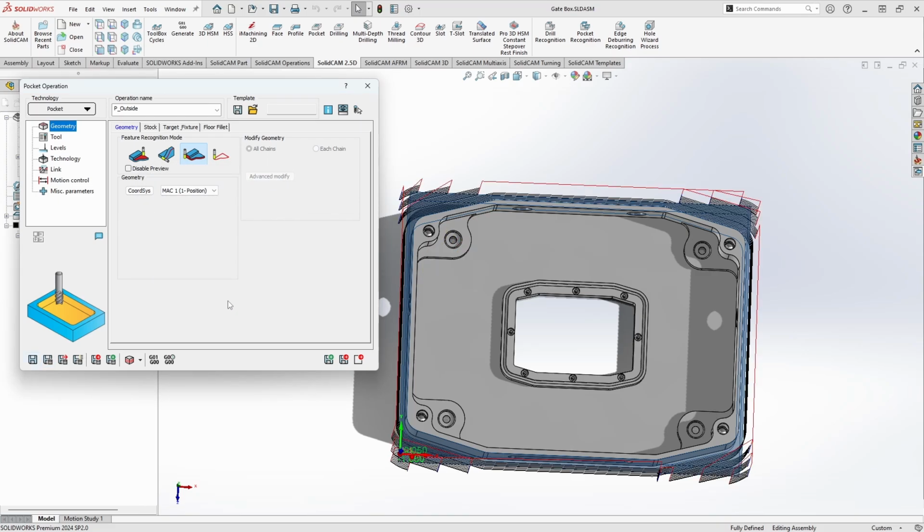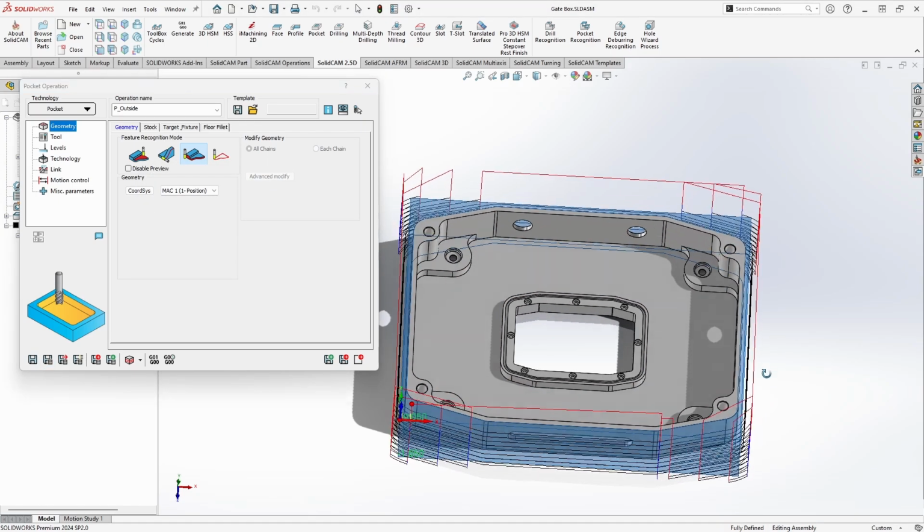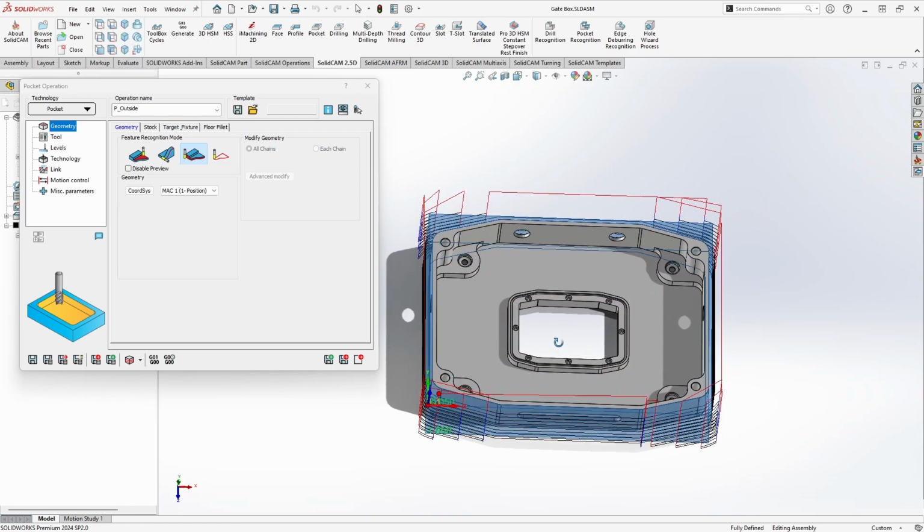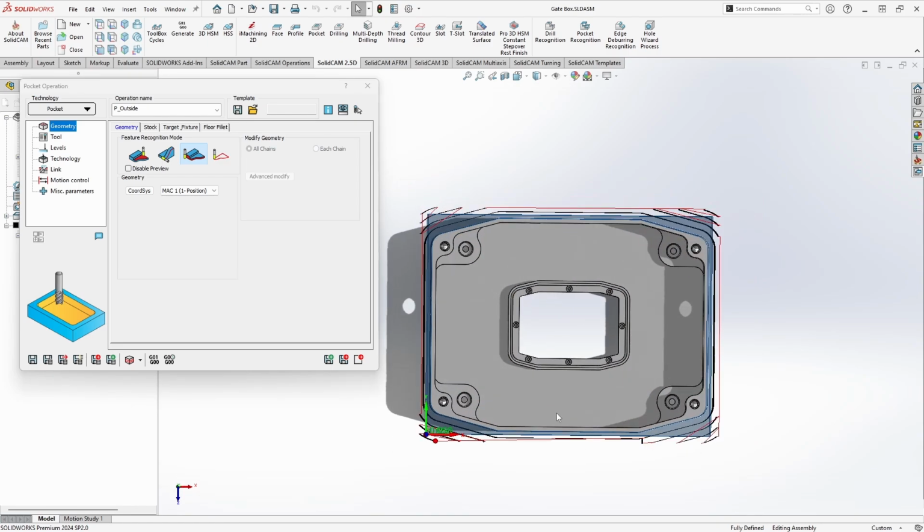you can see that we've generated toolpath only on the external sides of the part to remove all of the stock material that was present when we initially set up this CAM part. This is a super simplified one-click way of removing basically all of the external perimeter of a part without having to do any detail clicking at all. And again, this is fully stock aware, so if you've already done some prior operation, whether you've maybe machined out the center boss or something else, it'll notice what material's already been removed so that you're not air cutting that same material again.